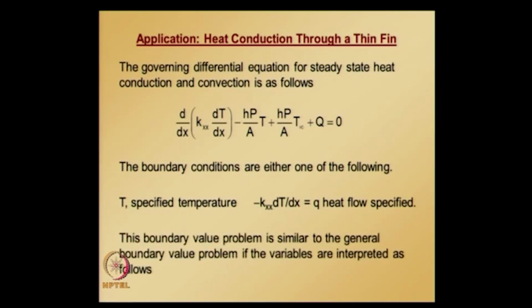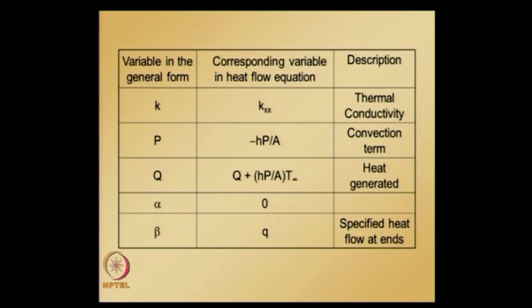So, we need to make a comparison between this boundary value problem and the general one dimensional boundary value problem. This boundary value problem is similar to the general boundary value problem if variables are interpreted as given in the table here, which shows a comparison of corresponding variables in the general form and the specific case of heat conduction and convection.